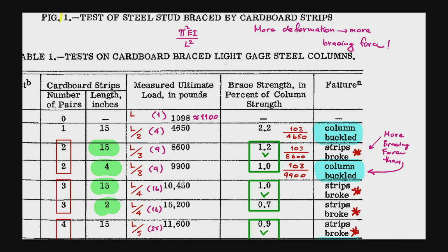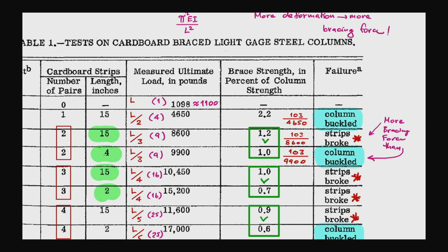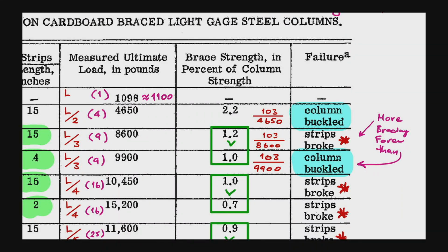You have to categorize the crack, flexural crack or shear crack, or is it caused by splitting and that caused the longitudinal cracking, right? Is the rebar buckling, is the rebar yielding? All of these failures of individual materials have to be well recorded in order to understand the phenomena and understand how things fail from the structural engineering point of view.